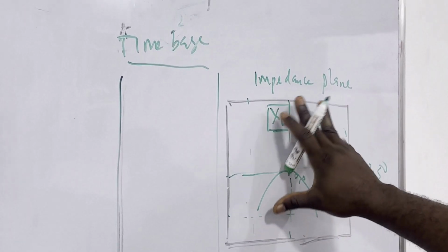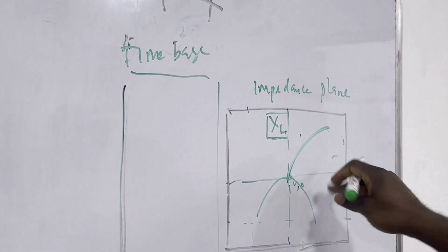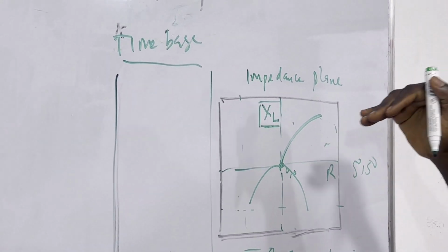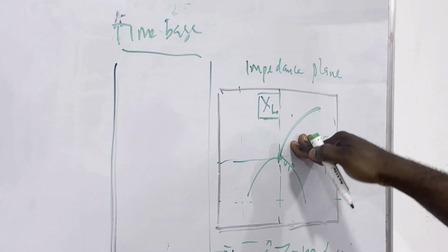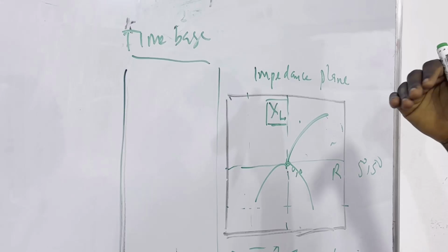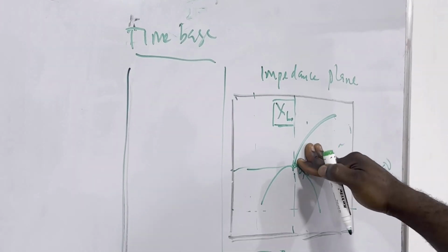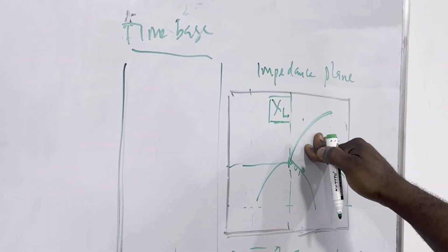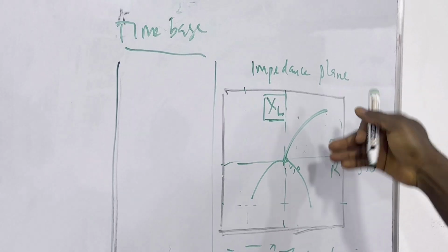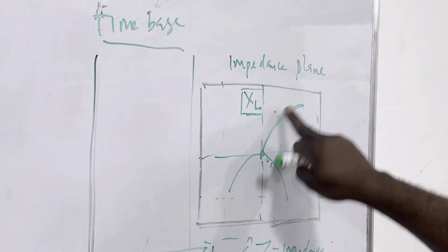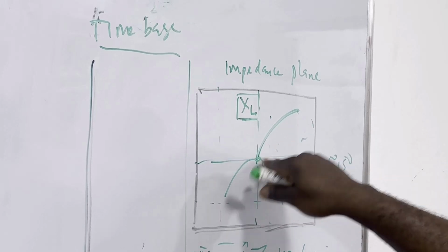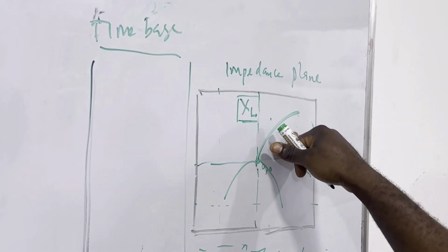So whatsoever indications are coming, whether it is due to the curvature of the material or due to the surface of the material or due to the weld toe or weld cap or whatever surface indication, or even due to real defects like a crack, they are all going to display as changes, as curves that will be coming out on your impedance plane.